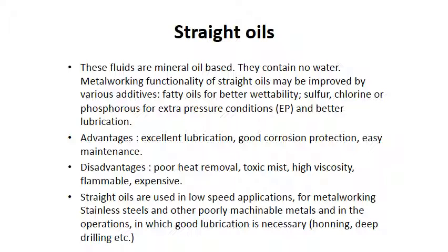The advantage of straight oil: the main advantage is excellent lubrication. Second is good corrosion protection and easy maintenance. The drawbacks of straight oil: poor heat removal rate, toxic and high viscosity, flammable and expensive.